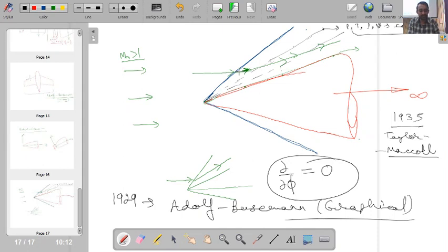In the two-dimensional representation, it looks like nothing but a single ray, because in the angular direction there is no variation, so whatever the property value over here is, the same will be the property value in the complete 360-degree rotation. So you can consider that the whole surface of the cone has the same value of the properties. Then outside that you can take another envelope, in that also there is a constant value of property, then another neighboring envelope, so likewise your property variation will travel from one envelope to another, but within a single envelope, because there is no variation in the angular direction, properties will remain constant.